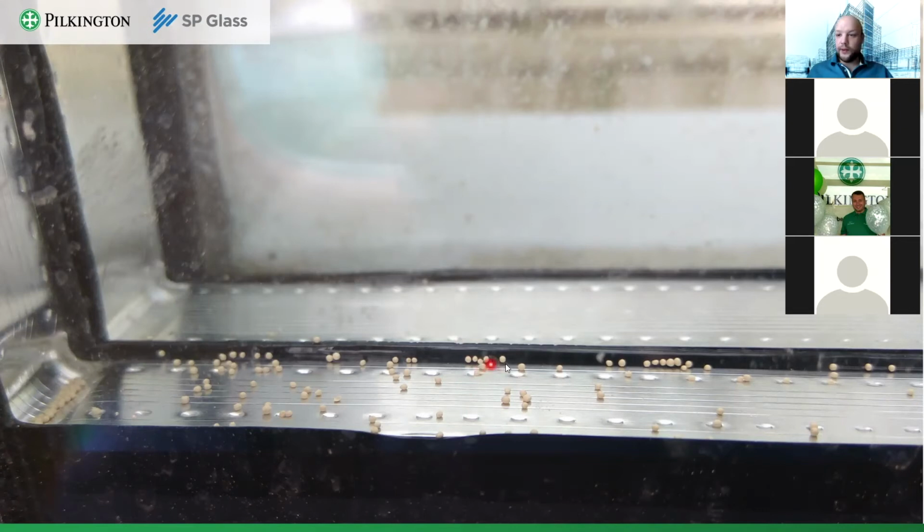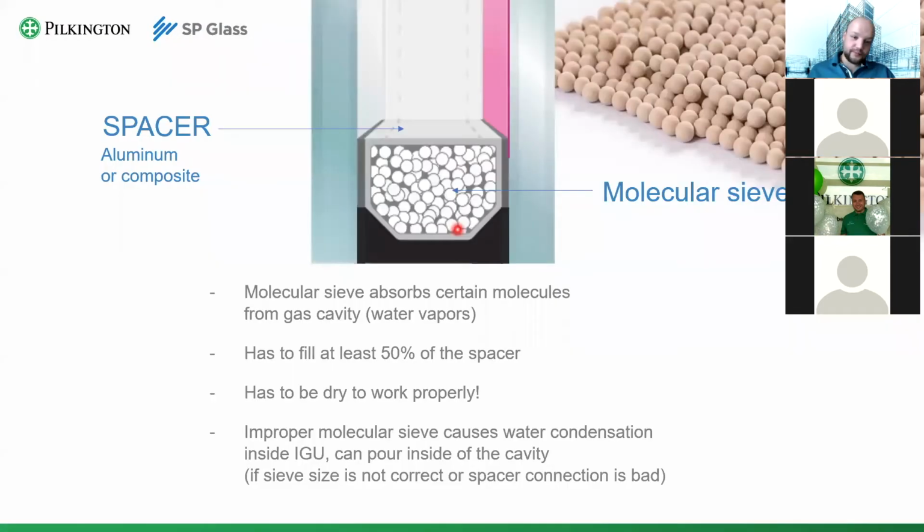Molecular sieve can be plagued with dust. Microscopic particles of this molecular sieve, during transportation, can get through the holes and be left on the inner surface of your IG unit, creating a dusty, whitish look. Obviously that is a defect of molecular sieve. So the only advice I can have is to use a good one. And in any case, watch for the molecular sieve, and it will perform perfectly until the sealing of your IG unit is breached.